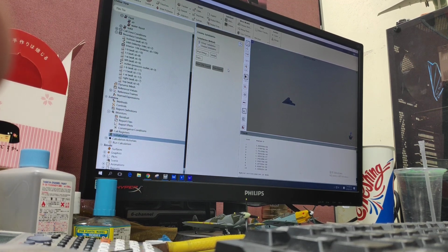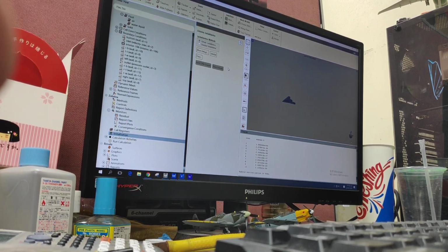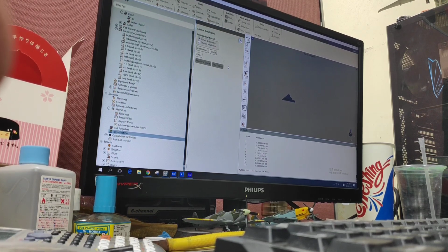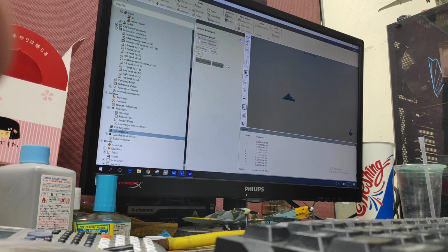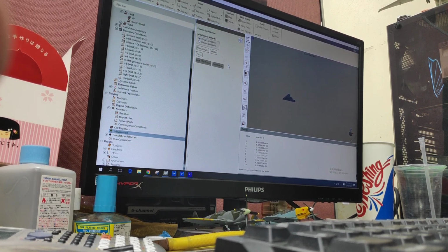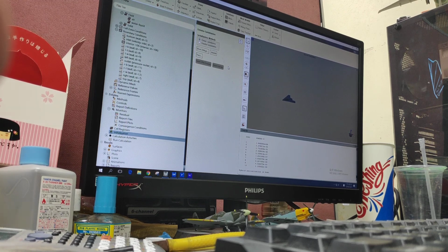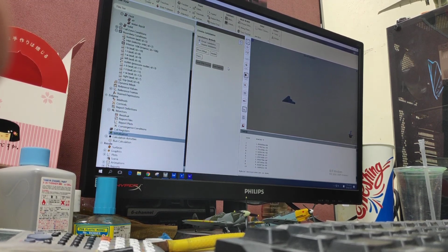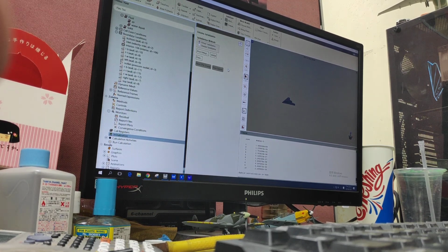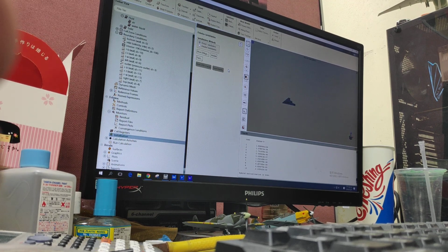So basically, when I'm trying to do the Fluent, I import the mesh. Not for the surface, it's your whole mesh with the flow domain, with the boundary layer growth, the one we did last time. Including that. But I don't see it here. Why? Because I hide it, because I only chose this one. Okay, so everything is initialized.